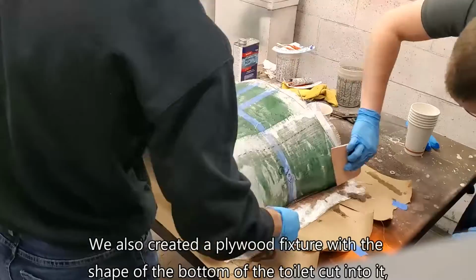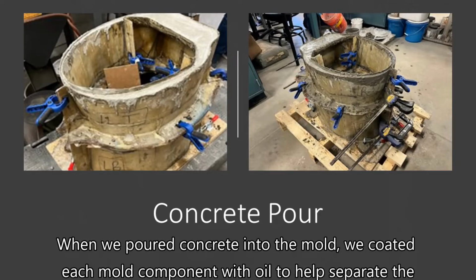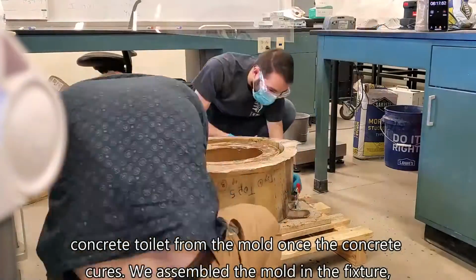We also created a plywood fixture with the shape of the bottom of the toilet cut into it, where the mold could sit. This keeps the inner and outer mold pieces aligned with one another. When we poured concrete into the mold, we coated each component with oil to help separate the concrete toilet from the mold once the concrete cures.